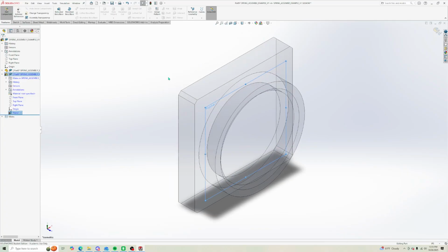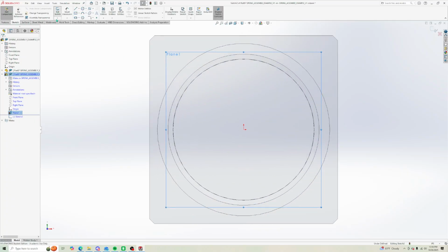Control 7, and what do we have now? Select the plane command from reference geometry, drop down list. Okay, that's step 6. Give me 1 second. So open a new sketch on plane 1. So it selected plane 1.